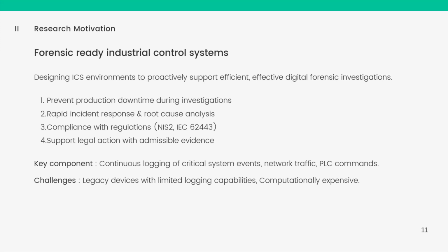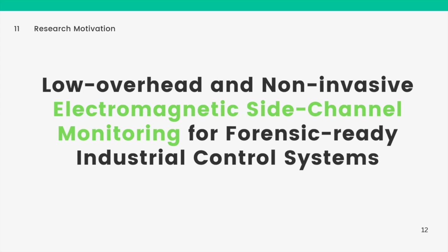So one thing that we can do in making our system forensically ready is like continuously logging the critical system events like network traffics, PLC commands. But the challenge that we have with this is these legacy devices that we have in industrial control systems don't have much logging capability. They have very less storage, and continuously monitoring traffic patterns, recording them is computationally very expensive. So we need a methodology that doesn't add overhead and make the network more complex. So that's where this electromagnetic side channel monitoring comes into the talk.